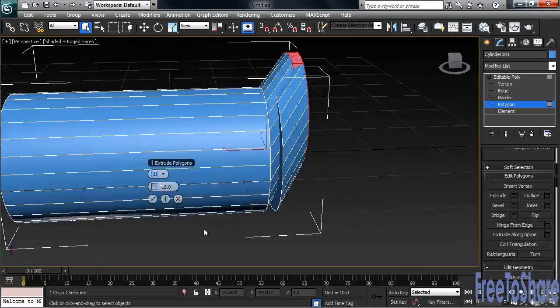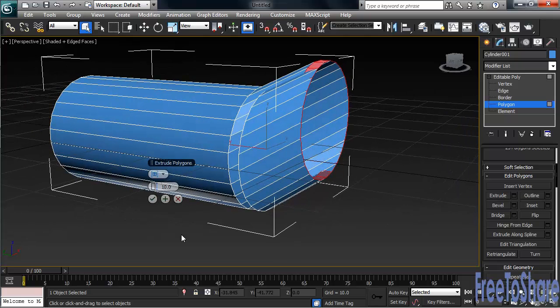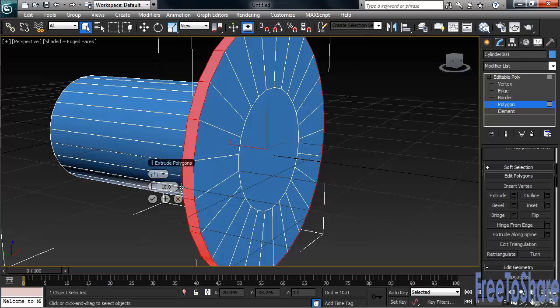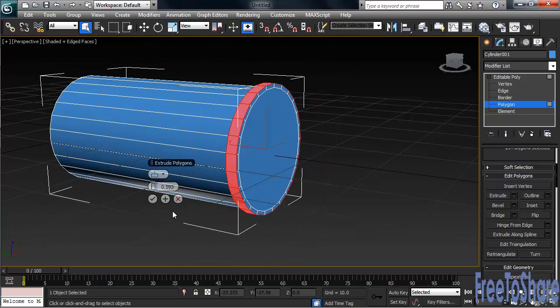You'll notice that when we orbit the view, the caddy stays perpendicular or flat with our window. What looks like a mess right this moment can easily be changed by going to the second row and changing to Local Normal. That will serve to push all the polygons out in a straight direction. Using the third level, the extrusion amount, we can now take that down. Why don't we settle in by typing in a value of 0.5.